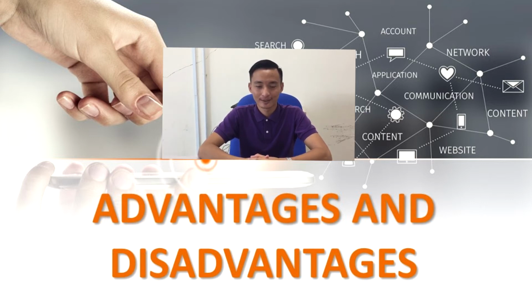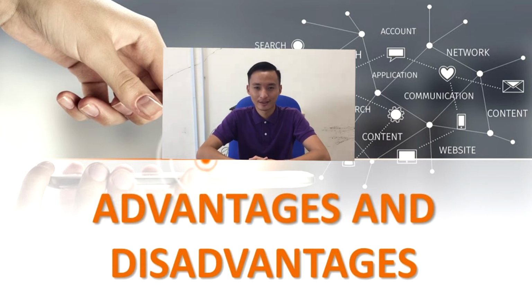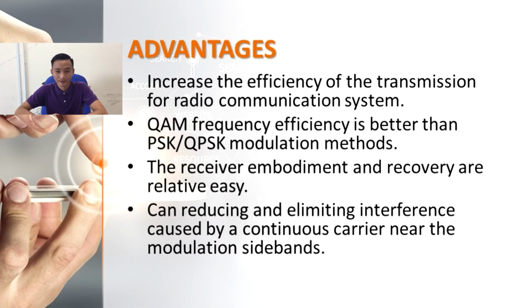Today I would like to present about the advantages and disadvantages of quadrature amplitude modulation. Firstly, the advantages. The first advantage of QAM is that it increases the efficiency of transmission for radio communication systems. Second, QAM frequency efficiency is better than PSK and QPSK modulation methods. Third, the receiver embodiment and recovery are relatively easy. The last is reducing and eliminating interference caused by continuous carrier near the modulation sideband.